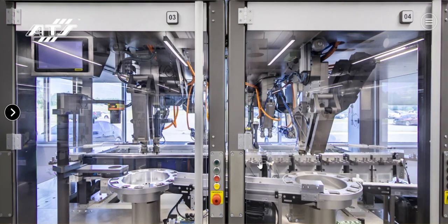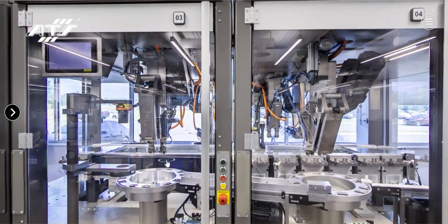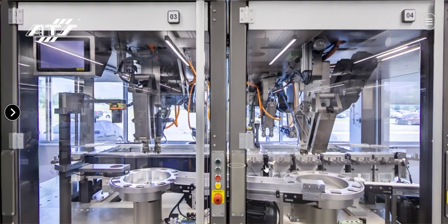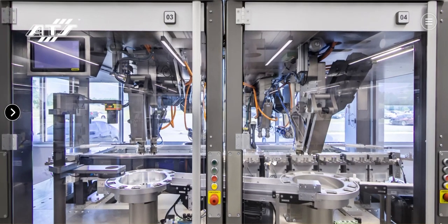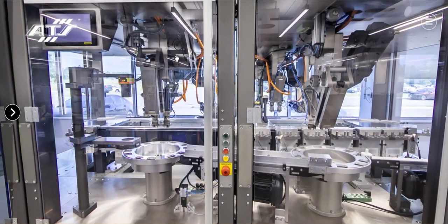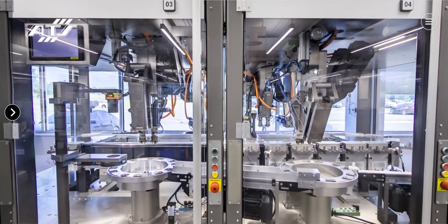giving them a very high degree of speed, acceleration, control of speed and acceleration, and of course positional accuracy, with the ability to stop pallets at any point along the track without need for external lift and locate mechanisms or things like that. So a tremendous amount of flexibility and capability built into the conveying system itself, moving these pallets around from station to station. The next thing you'll notice is that hanging from the ceiling are a series of very similar, in fact, from a base perspective, identical pick and place robots.